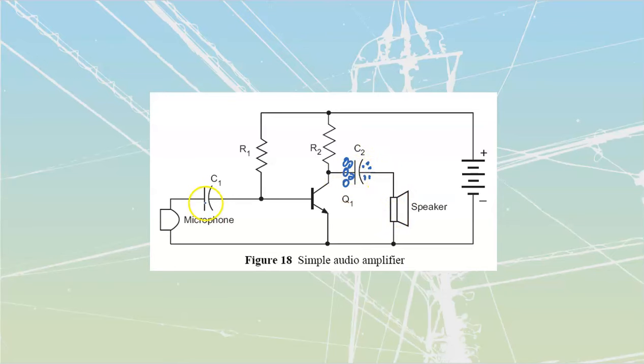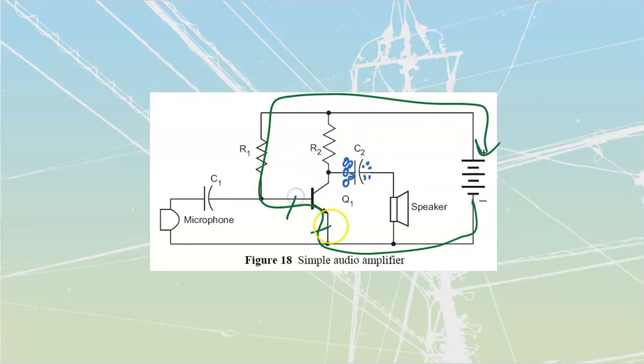What about on this one? Well, the instant that we powered this up, we would have had a current established through here, like that. What is this? VBE, voltage from my base to emitter. You know this, 0.7 volts. If I take a look at this, I see that this circuit from here to here is in parallel with that 0.7 volts. So what is this cap going to do? It is going to charge to 0.7 volts.